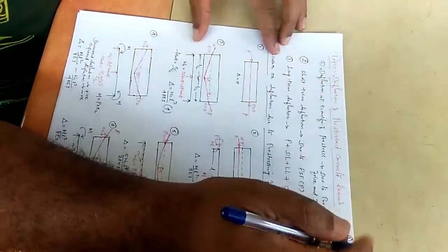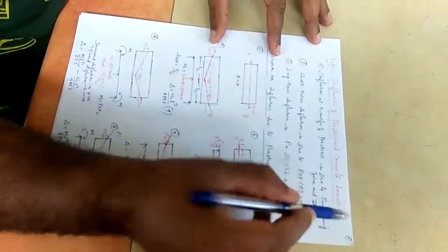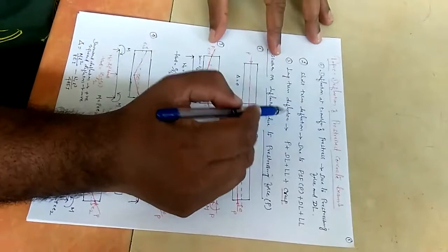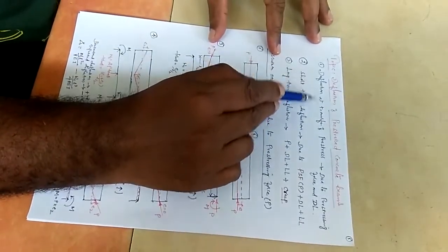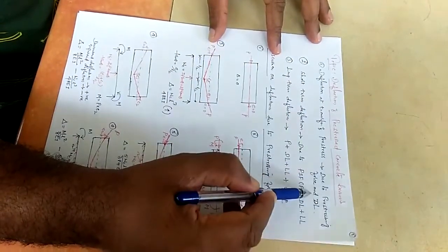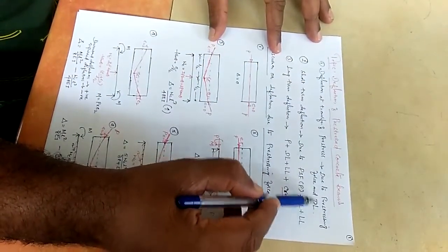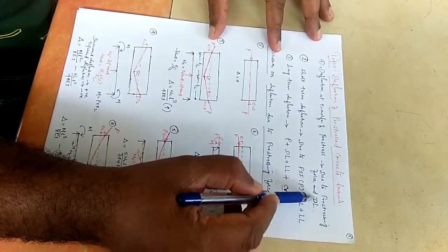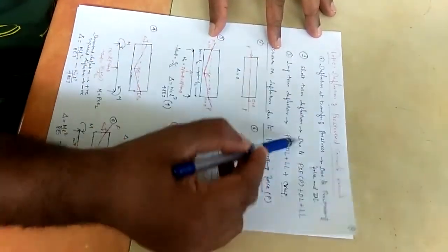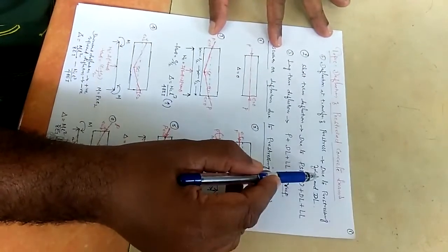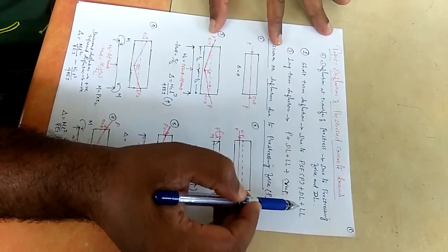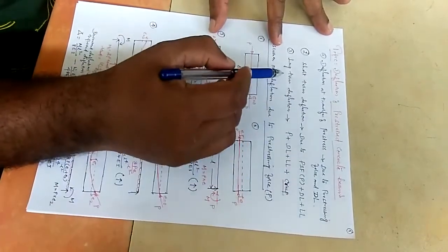Okay, welcome to today's topic, deflection of prestressed concrete beams. There are several reasons for deflection. One is deflection at transfer of prestress, that is due to prestressing force and dead load. During the transfer of prestress, dead load is there. Second one is short-term deflection, that is due to the above, prestressing force and dead load, with external load, that is live load.